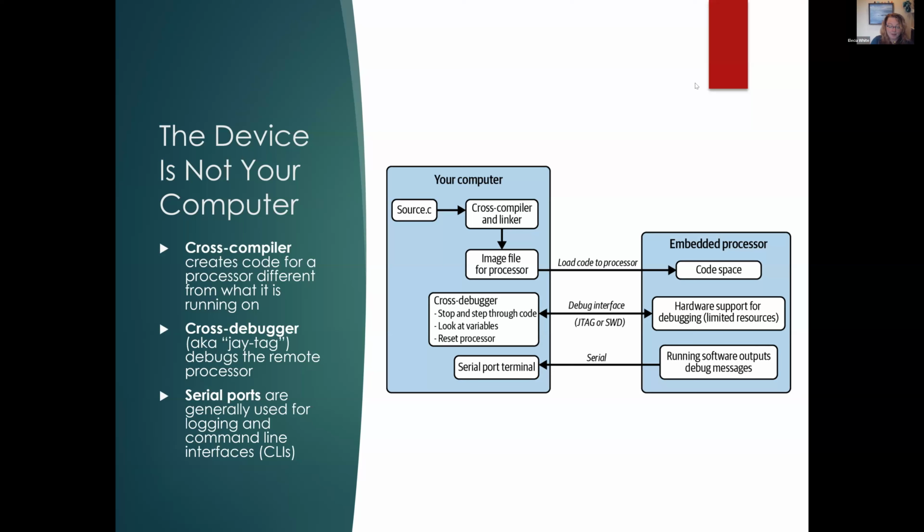They use cross compilers. A cross compiler runs on your desktop or laptop computer, but it creates code that does not run on your computer. Instead, that image runs on your target processor. These compilers are sometimes quite expensive and provided by the processor vendor or a third party that works closely with the processor vendor to get all of the pieces right so that this is easy for you to do. Compilers may also be free, a GCC variant that you simply need to set up properly, something that can be much harder than it sounds.